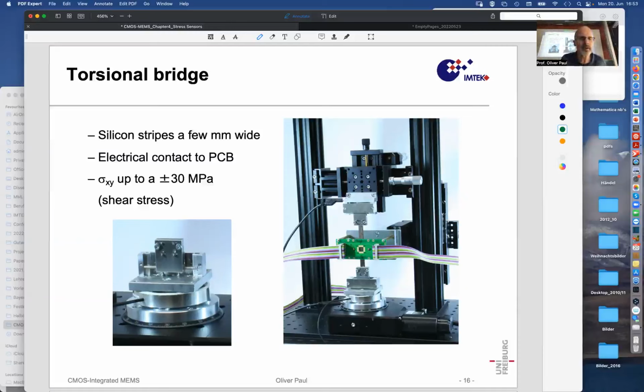Where is it? So there is an axis. Let's make this in another color. So here is an axis that can rotate, where this structure can rotate back and forth. And of course, it can also move up and downward here, slide up and downward. So this can also move in this direction. That's pretty much what you need to remove other degrees of freedom. The same structure is also implemented up here. So this is released except for the rotational degree of freedom.